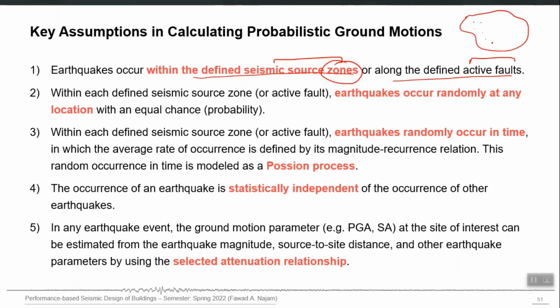So I plot all 100 years of earthquake data, and let's say these dots are all the epicenters. Then I will carry out a detailed study to identify the seismic sources, and I will come to know, let's say, that there is a fault line here which produces most of the earthquakes which occur in its vicinity. There is a point source at this location and at this location, and that point source produces all those nearby earthquakes. This one also produces nearby earthquakes. This is the fault line.